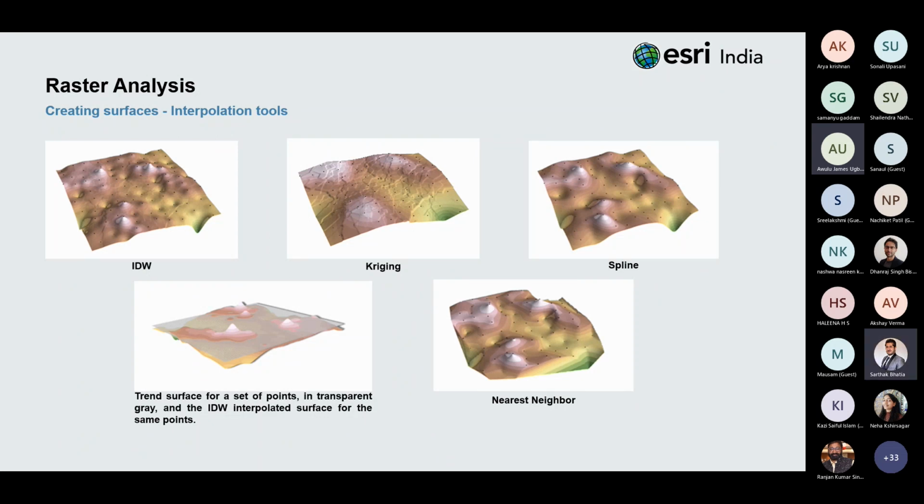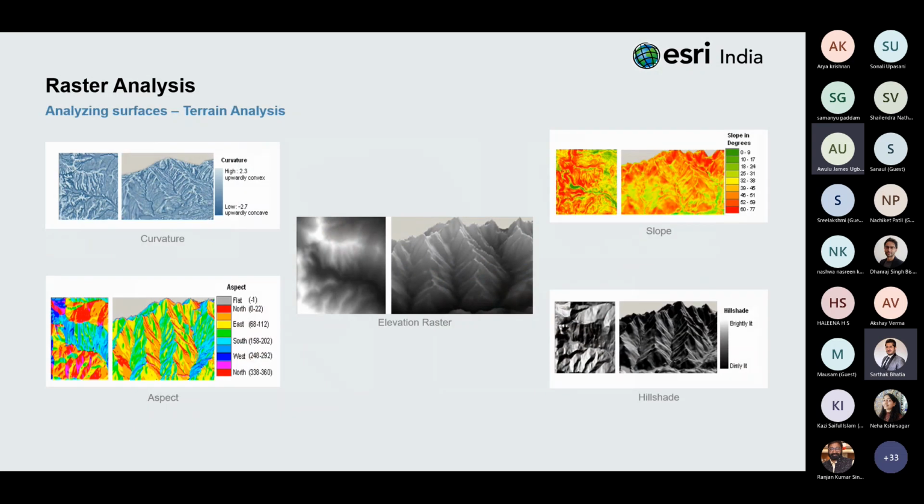For creating these surfaces, there are multiple tools which are primarily used in the form of analysis. These tools are slope, aspect, hillshade, and curvature. The slope tool calculates the maximum rate of change from its cell to its neighbors, which is typically used to indicate the steepness of terrain. The aspect tool calculates the direction in which the plane fitted to the slope faces for each cell. Now, the aspect of a surface typically affects the amount of sunlight it receives, as does the slope.